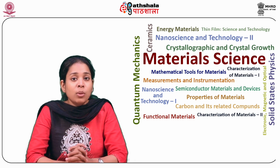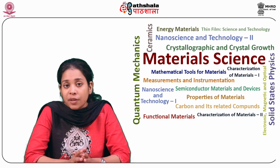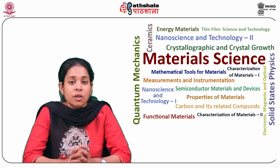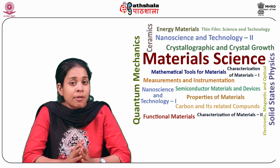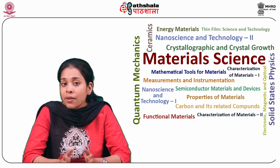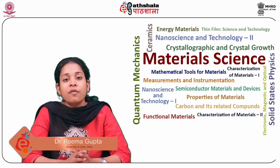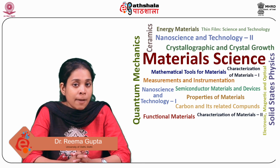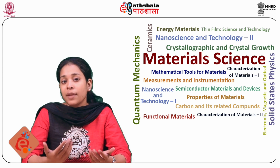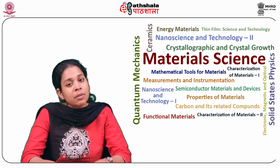Then we have discussed the waveguides for the different configurations. The different possible configurations are the strip line, microstrip and coplanar waveguide resonators. Here coplanar waveguide resonators are represented by CPW resonators. And we have concluded that among the three resonators, the coplanar waveguide resonator is the most successful geometry for the transmission of electromagnetic wave in the microwave region from one point to another. So in general, the coplanar waveguide consists of a center conductor with two ground planes printed on the same surface of a dielectric slab.